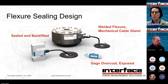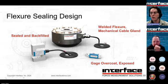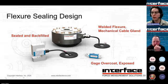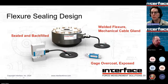And it really depends on the application, right? So we have some load cells that are being used in oil drilling applications with 20,000 psi of oil around it. And then on the other side, we have load cells that are being used in high vacuum environments where everything needs to be vented and outgassing is a concern. So really working with the applications engineer on your unique environment and use case is really important in getting a load cell that's going to be good for you.